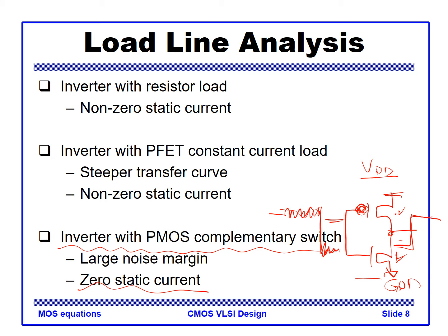We will go through the noise margin definition later, but for now just remember that the inverter with a PMOS complementary switch will have zero static current. That's pretty much the most important feature, which is why modern technology utilizes this complementary logic style.